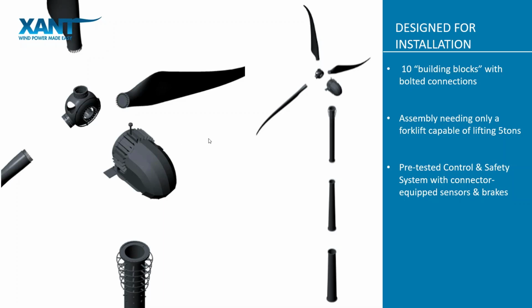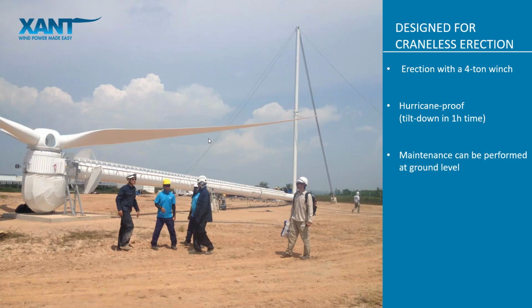And then, most importantly, once you have your turbine assembled, how to erect it. This is where we obviously differentiate from larger machines: we are always able to tilt up the turbine with a simple 4-ton winch, which is a very standard piece of equipment. This avoids bringing a crane to the site, which can be an enormous cost in some locations, or even a close to impossible challenge.